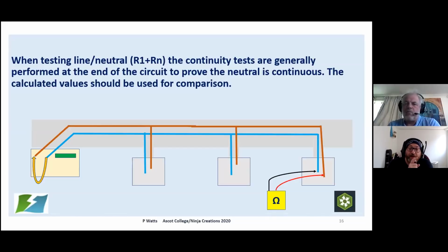I'm not really... Go on. But once you've made your final decision, and it takes a while, on the number of protective conductors and the size of the wiring system, it can be done. They're just different resistivities to combine in parallel, aren't they? It's a calculation I'd like to avoid, though, to be fair. It's a can of worms, because how many connections have you got? How many connections have you got to the trunking?